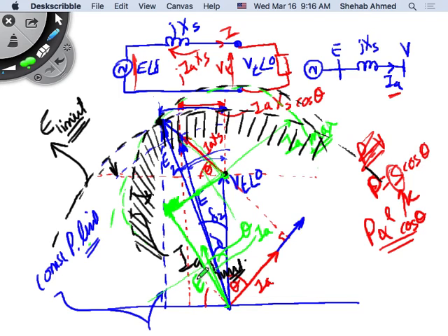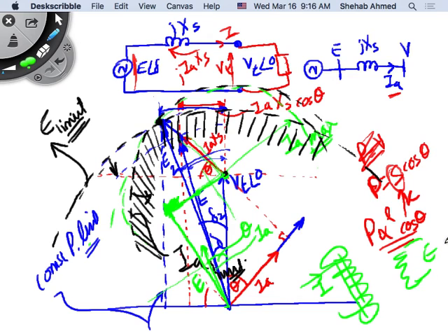How do you decrease E physically in the generator? Remember, you have a field winding on the rotor. All you can do is control the current, right? You control the current, it will control the voltage induced across the stator windings. That's all you can do, right? So how do you do this? Here, E changed in magnitude. I decreased E. How do I decrease E? For me to decrease E, I decrease I, right? What happens if you keep decreasing E? You keep decreasing I.